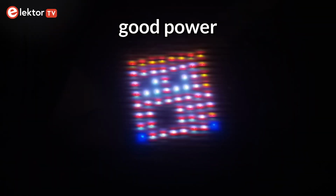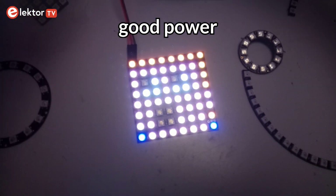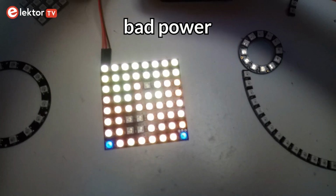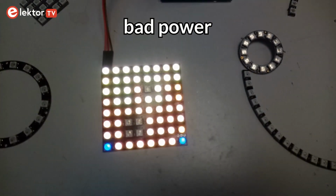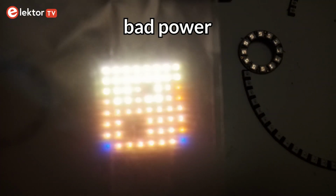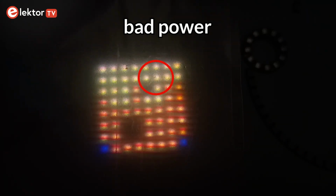Another important thing is the power supply of the LEDs. This is valid for every design using them. When there are many LEDs, or when the light intensity has to be high, or when there are many white pixels, you must power the LED strip directly from a good 5-volt power supply. Note that the value of the supply voltage of the SPI converter must be the same as that of the LED strip.